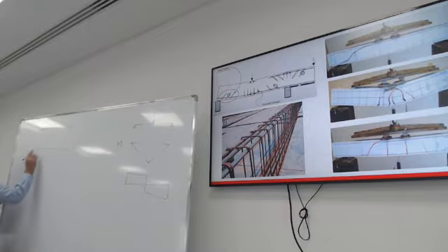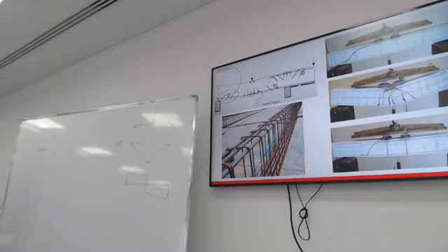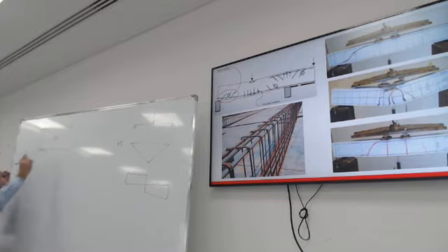So this is the beam. It is sitting on a support here, and this is the support. What is going to happen is there is a little element. From the left hand side, it's feeling the shear going upward. From the right hand side, it has the point load going downward. So it has two equal and opposite forces trying to cause shear. If you look closely, this will turn into a couple that wants to turn or rotate this element.